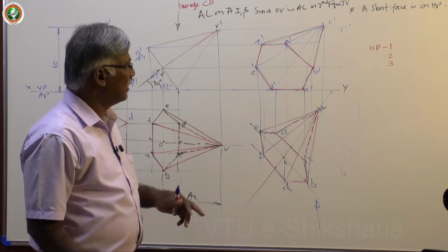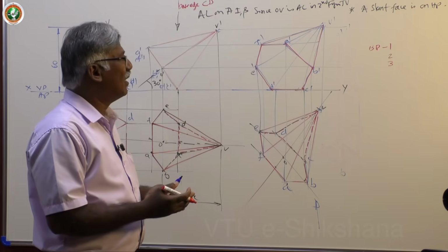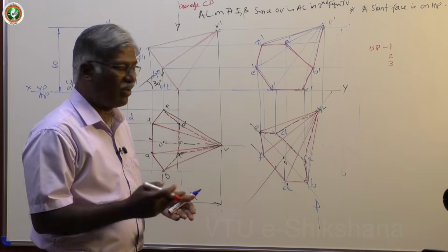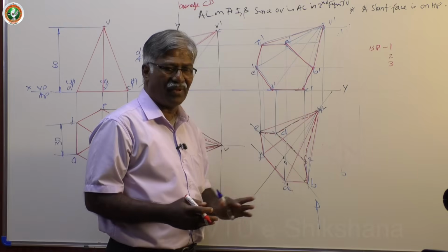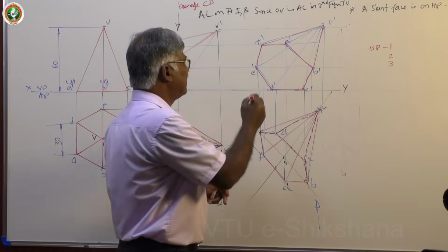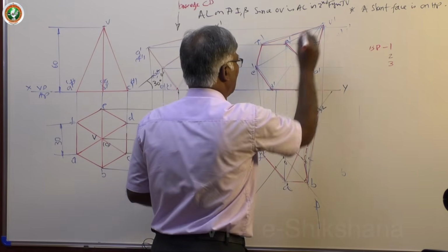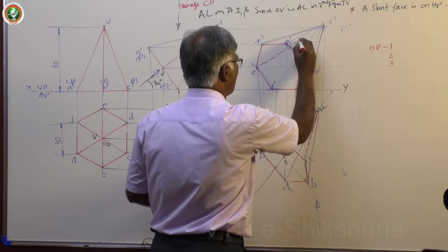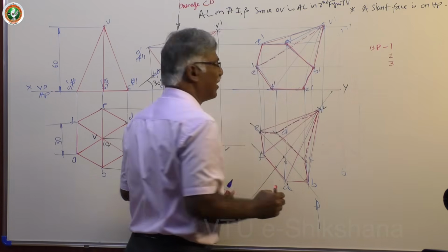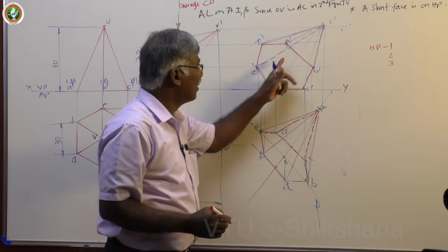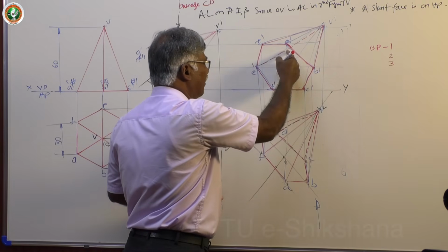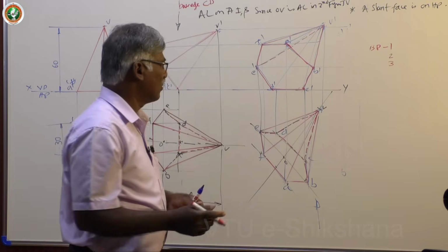Now the rest of the procedure is very easy: either crossing line or bends, or visible surface, invisible line. Now see, EV is dotted because it is an invisible surface, you cannot have a visible line or crossing line. This is a dark line already, you cannot have one more dark line passing through that.